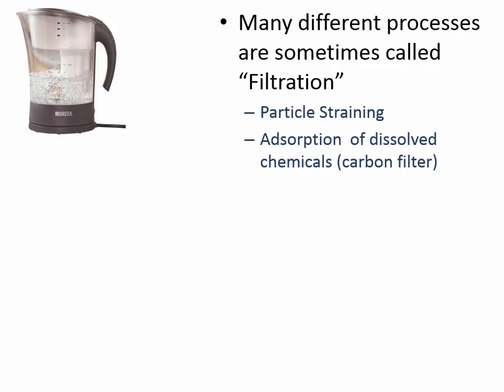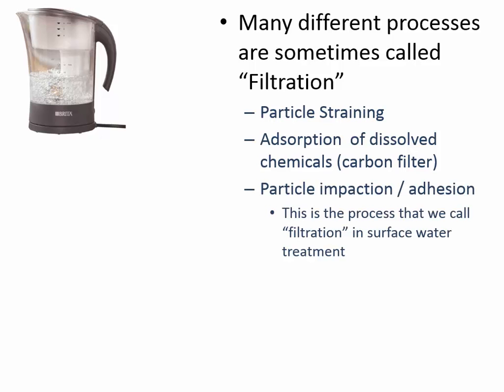Sometimes we also talk about filtration when it's a chemical adsorption. And earlier in the semester we talked about activated carbon and how organic chemicals will get onto the surface of activated carbon. And that's not the kind of filtration we're talking about either. What we're talking about is particle impaction and adhesion.